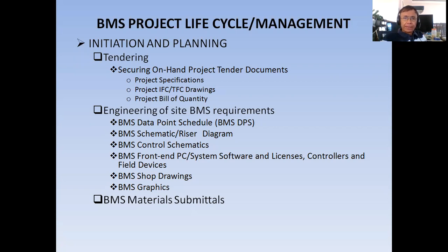Okay, now that is the tendering part. So if you are the BMS engineer of a solution provider, you will go to the on-hand project, then ask for these tender documents. Now, once you have these tender documents, you can start the engineering of site BMS requirements. In this engineering work, you should be able to produce the following: BMS data point schedule or BMS DPS, BMS schematic riser diagram, BMS control schematic, BMS front-end PC system software and licenses, controllers and field devices selection, BMS shop drawings, and BMS graphics.